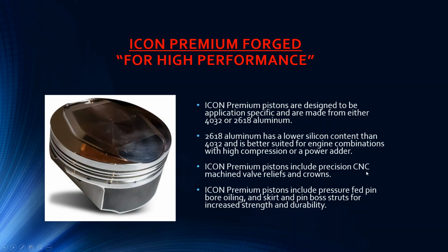Everything is precision CNC. By the way, all of our skirts are produced on CNC machines that have tolerances to 1/10,000ths. It's all in a controlled room environment at 70 degrees. So that reduces any variation in the machining, as well as the sizing of those pistons.